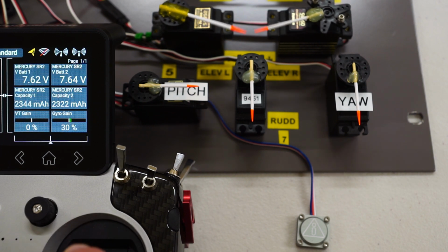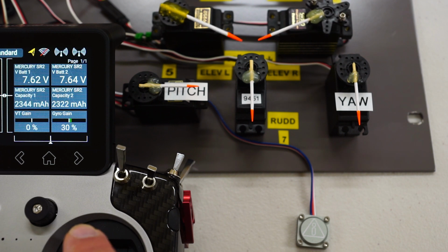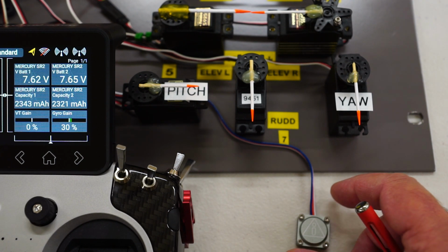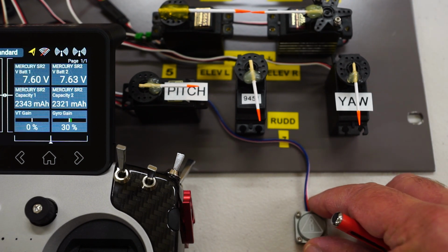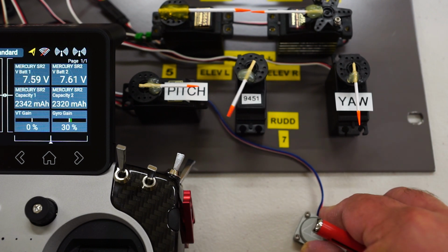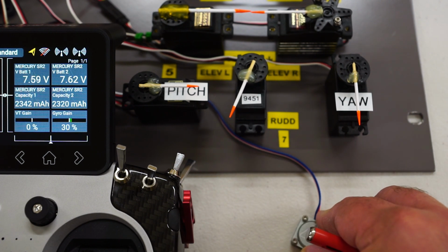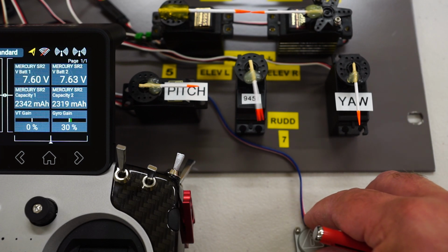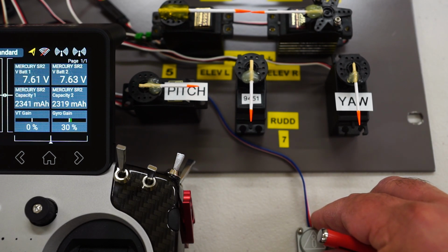However, you'll notice the pitch servo is not moving at all. And same goes for the rudder. If I move the rudder stick, now we just have basically the rudder servo moving, and no yaw action on the vectored thrust nozzle. And of course, since we've also disabled the gyro gain, if I put in some yaw movement, it's only impacting the rudder servo, so that's controlling our rudder in the correct direction. However, the yaw servo's fixed, it's not moving, which is what we want.